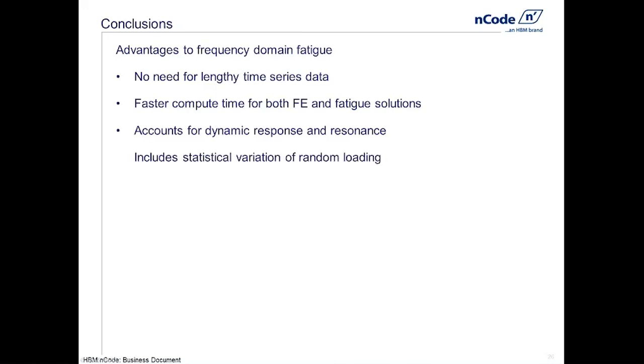And then lastly, we can look at the statistical side of loading, because remember we looked at this a couple plots before of, say, wind gust loading. The longer the sampled data in the time domain, the better statistical understanding we'd get of how often the big gusts happen versus how often the small gusts happen. PSD loading and PSD cycle counting techniques can inherently have that statistical variation built into them. And this is a great thing because now, in a compact way, the PSD can represent loading, and the rainflow cycle counting of a stress PSD can account for statistical variability.